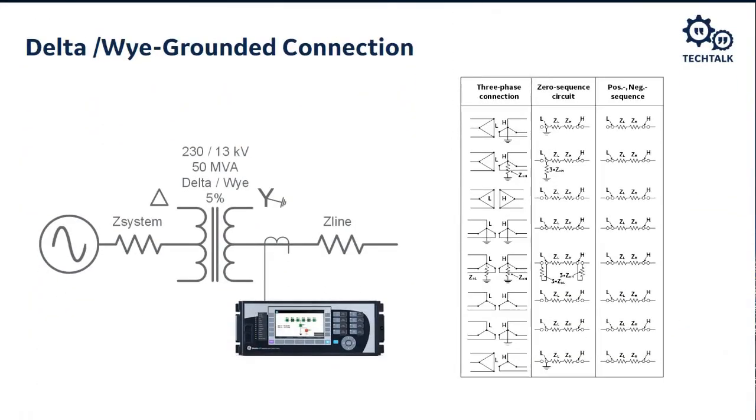Okay, so there's a monkey wrench that we're going to throw into this. The monkey wrench is that transformers can affect the impedance of our sequence networks. What I mean by that is we intentionally use transformers to block zero sequence quantities, right? If we look at this transformer that I show on the right over here, it's a delta to Y transformer. The Y is grounded. It looks like it's solidly grounded.